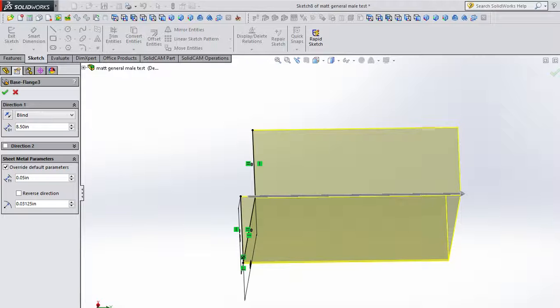But what we'd like to happen is if I change those 3 parameters on this part, the female part, or the outside part, adapts and all the holes line up every single time. That way we can make an infinite amount of boxes by only changing 3 little parameters. It's really fast rather than building a whole new model every single time. So that's what we're going to do.